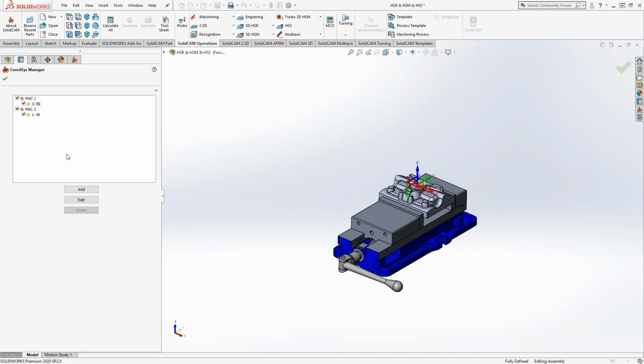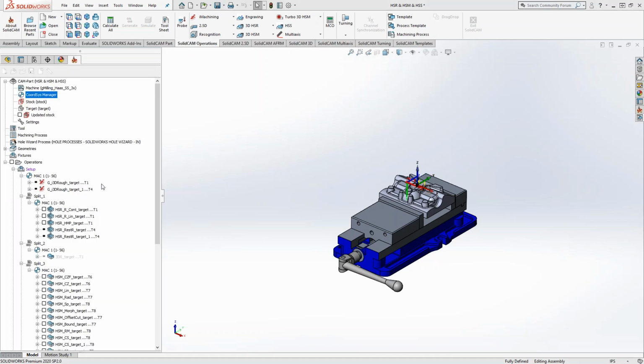And then what Jake was getting when you were doing your 3 points, you can actually do that off of sketches as well. So if you guys are trying to create a coordinate system in a specific way, you guys can create those sketch points or sketch lines inside SolidWorks and use that as your reference geometry as well.